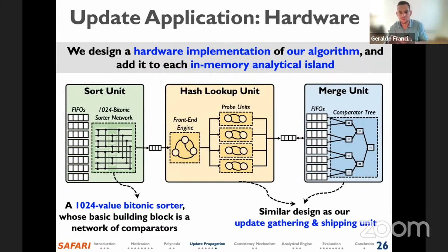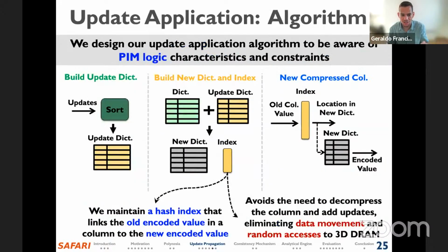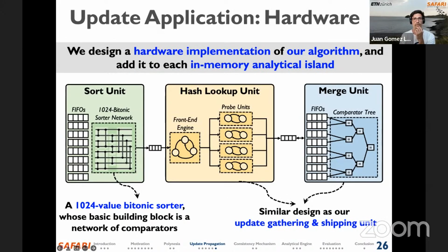That is why we need to do hash lookups super fast and maintain a high throughput. Over here, you are using this hash unit only for compressed dictionaries. Even though this can still be a bottleneck, the space is much more limited, so we don't need to maintain such a high hash lookup throughput. So we simplify the hardware a little bit and can save this reorder buffer.